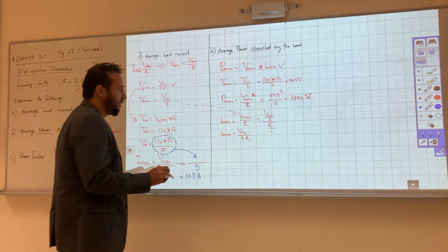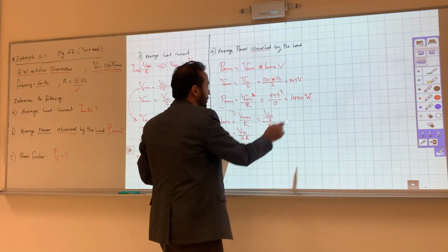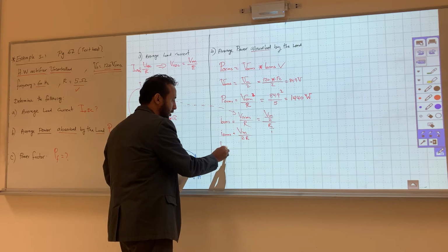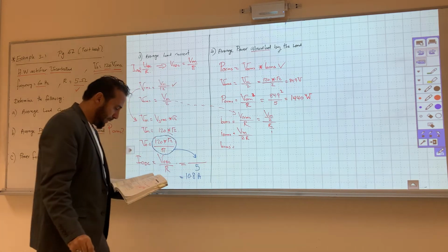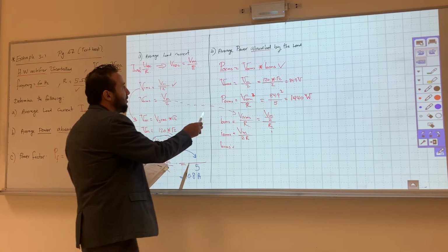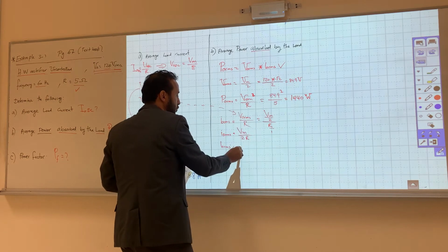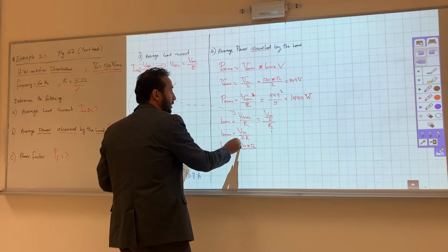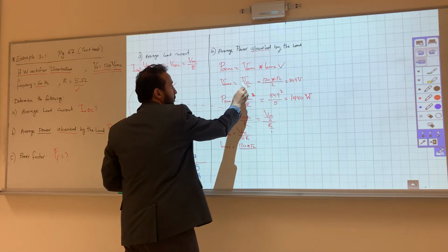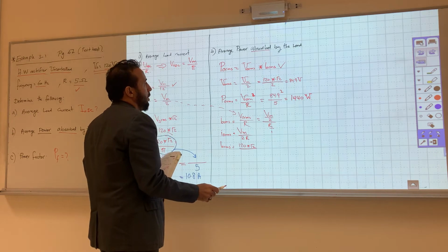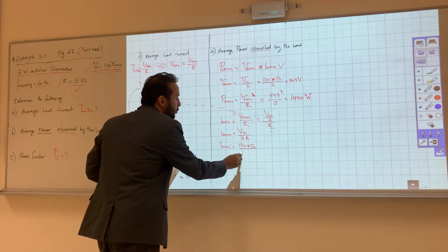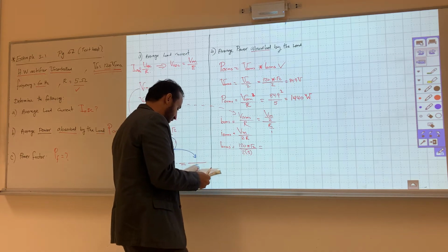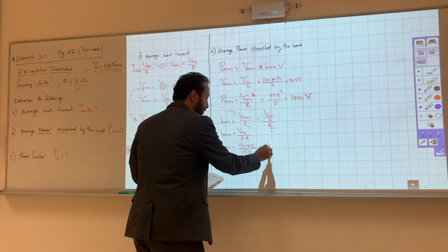So we can find I out RMS. If we want to use this equation, it will be the same. So now what's I out RMS? I out RMS equals Vmax. We know we have Vmax. How much is Vmax? Vmax, this one here, is 120 times square root of 2. Divided by 2 times 5, which is 10. So in this case, it will be 17. So this is 17 amperes.